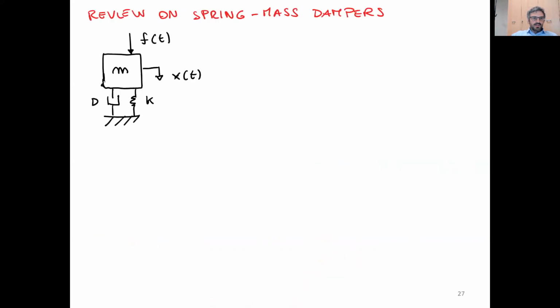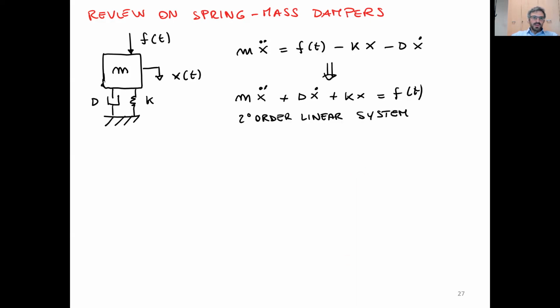These are just relations, and if we review how a spring damper is modeled this way, we said that this is a typical second order system. Let's see how it's possible to express it as a second order system and find out what are the natural frequency and the epsilon, the Z, the damping ratio, and the responses for this system.